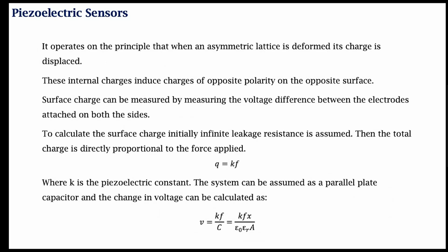So there are two resistances: the resistance of the electronics or the interface system, and the input impedance. So you need to find the effective resistance, and this corner frequency, that is the lower cutoff frequency, the low corner frequency, fC is 1 divided by 2 pi RC.